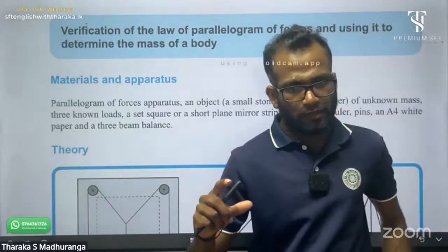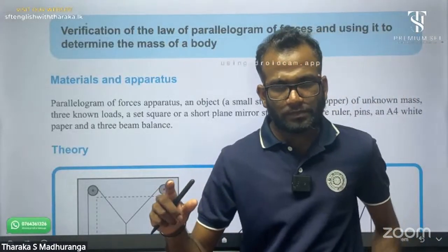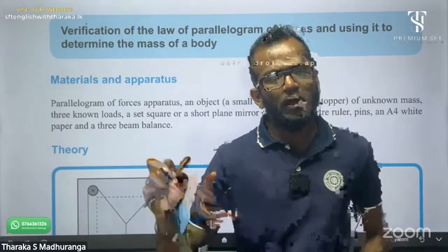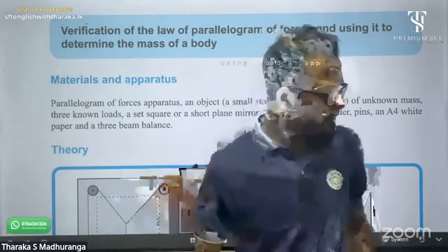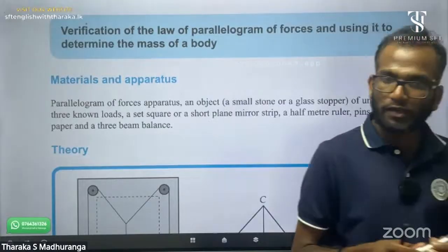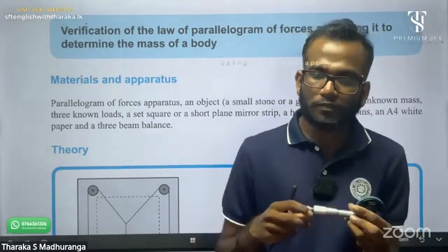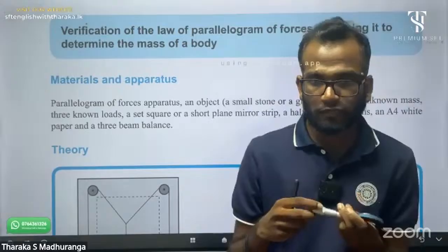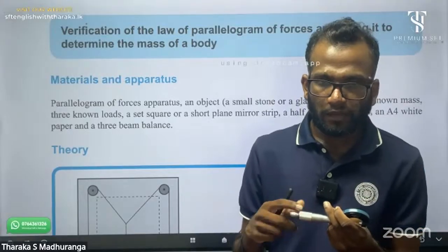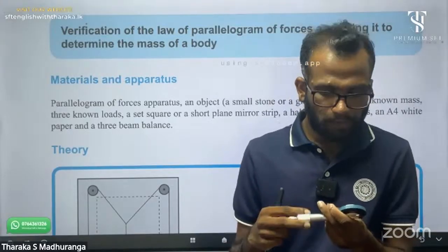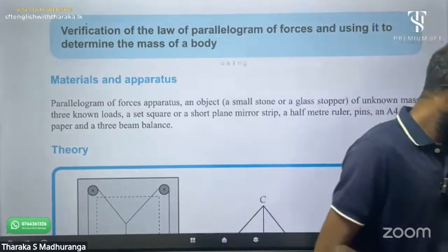In the micrometer screw gauge also, if you want a more accurate, more reliable measurement, we can take several readings, up to 3 or 4 times, and then get the average value, the mean value. That is also a recommended method in practicals.